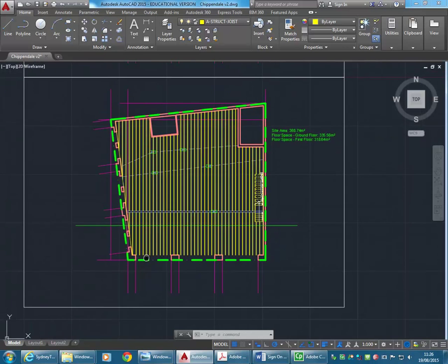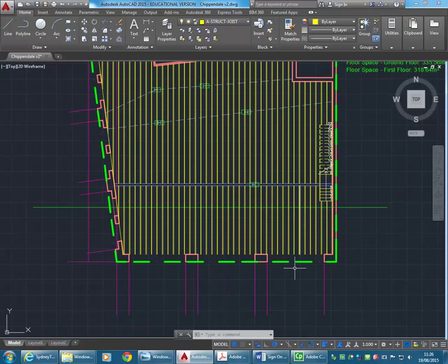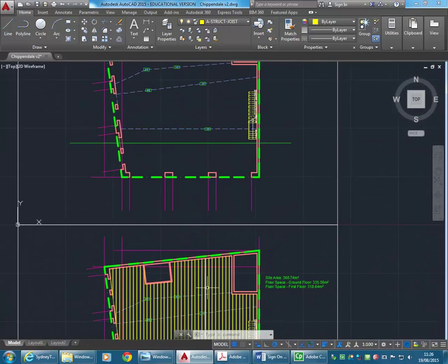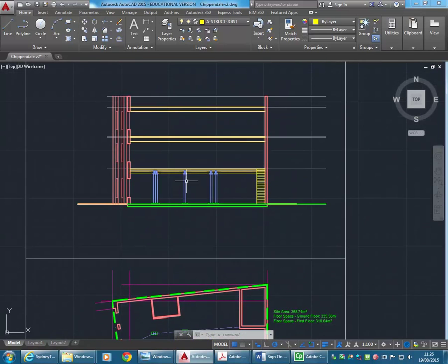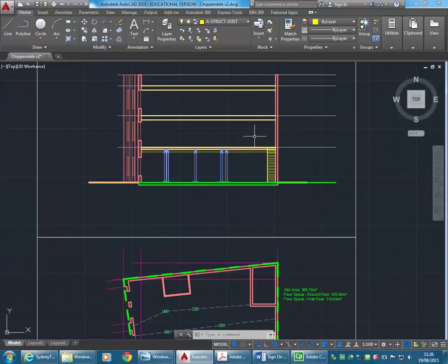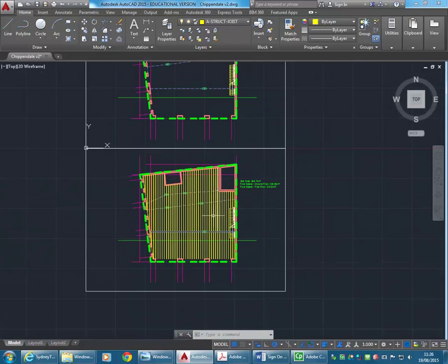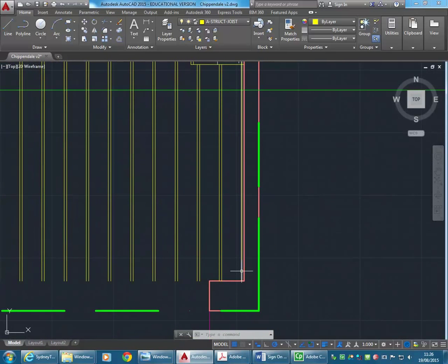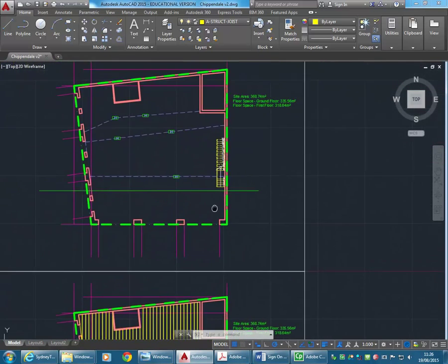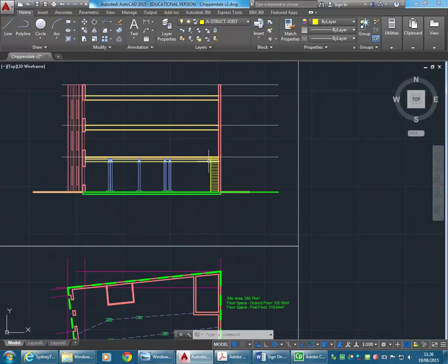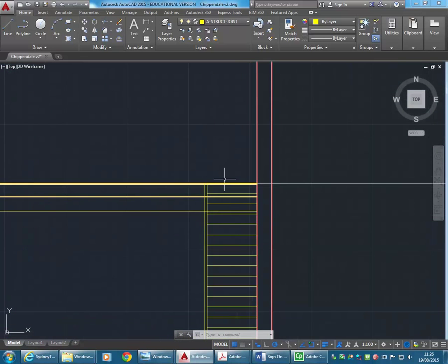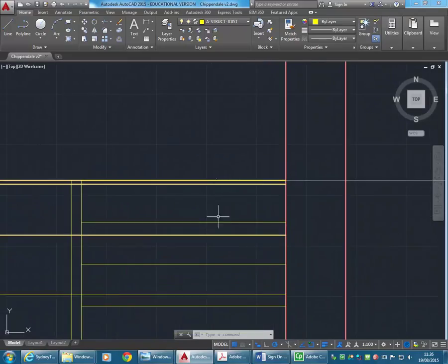So that's enough to then get going back with the section and finish that off in large part, or just for this level, and hopefully it can be largely copied up to the levels above. So the joists. Right, so we know that we have a joist on the right hand side, and I could project lines up, but we know the spacing, so it's probably just easier to draw in the section view.